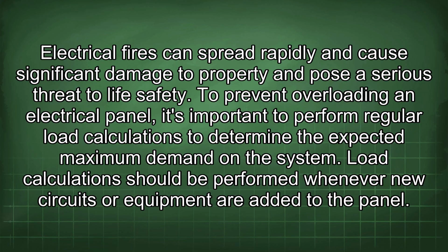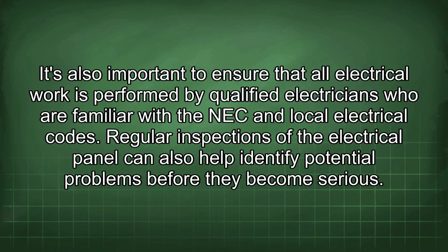To prevent overloading an electrical panel, it's important to perform regular load calculations to determine the expected maximum demand on the system. Load calculations should be performed whenever new circuits or equipment are added to the panel. It's also important to ensure that all electrical work is performed by qualified electricians who are familiar with the NEC and local electrical codes. Regular inspections of the electrical panel can also help identify potential problems before they become serious.